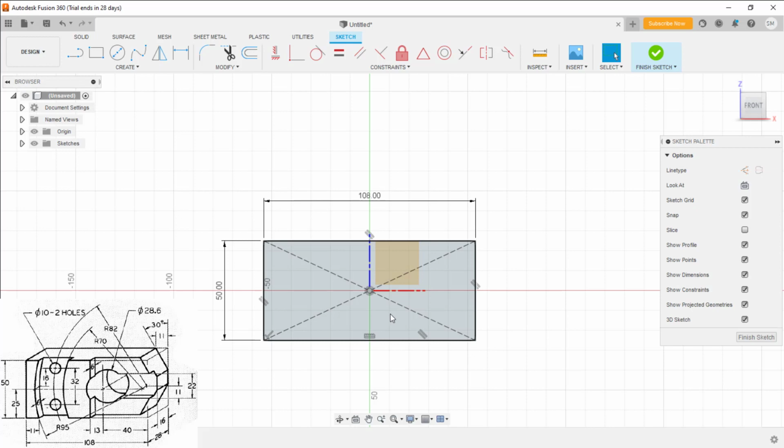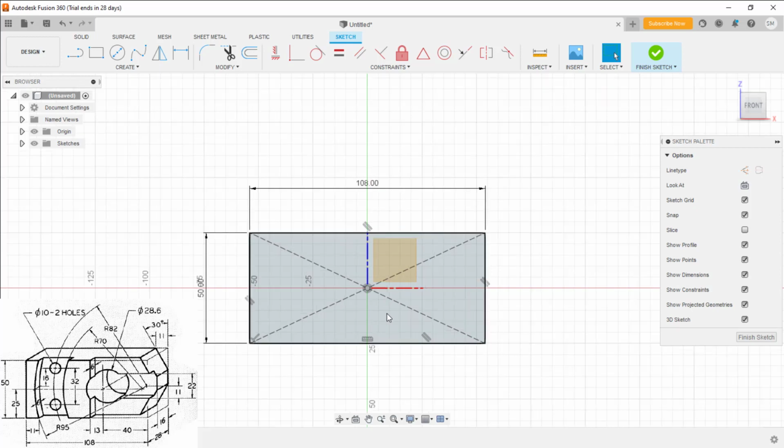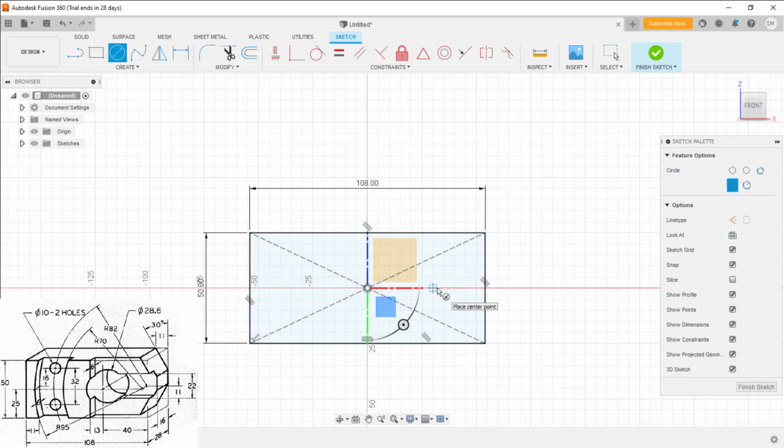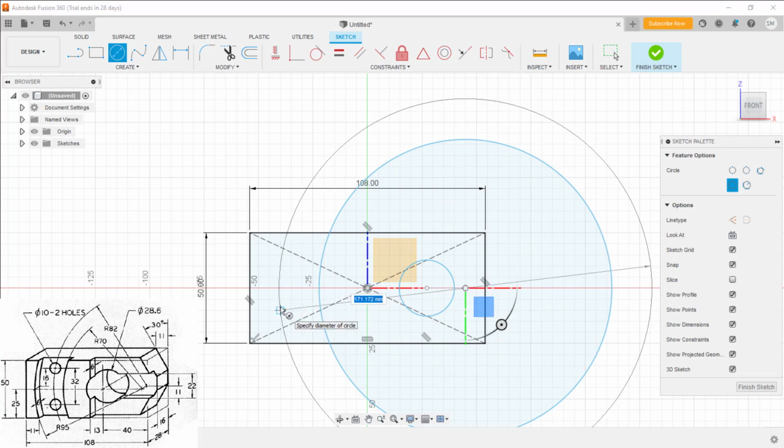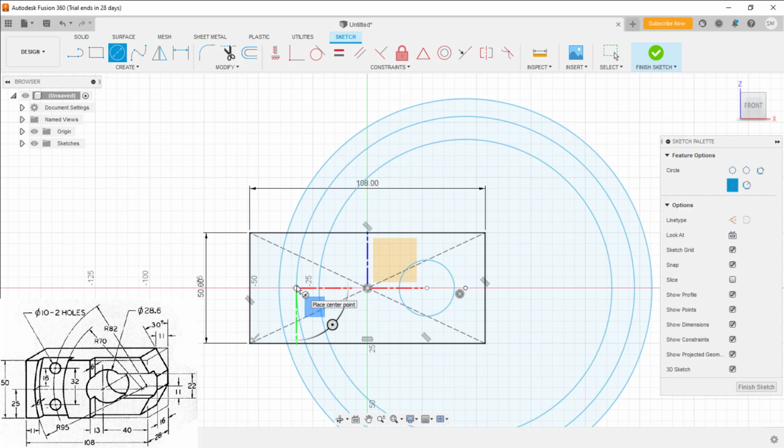so next thing, you can draw the whole sketch in one shot as we have the contour recognition here. So the circle, C shortcut, somewhere here I'll draw it. Dimensions you can directly specify or later on also you can enter it. From here somewhere I'll draw three circles to deal with these arcs. There are three cutouts, right? And this circle as well, the diameter 10 it is.